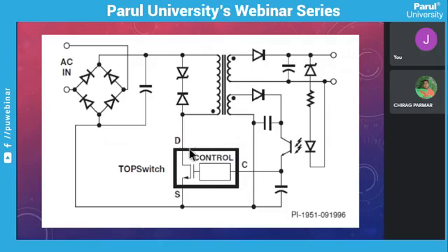So here is the thing. The pulse DC is applied here, and a pulse DC is received at this secondary. So this is the secondary. The secondary uses a diode for rectification of that pulse into almost a continuous DC, and a capacitor is also placed. And this is the auxiliary of the pulse transformer. The auxiliary is used for powering up the isolation barrier.